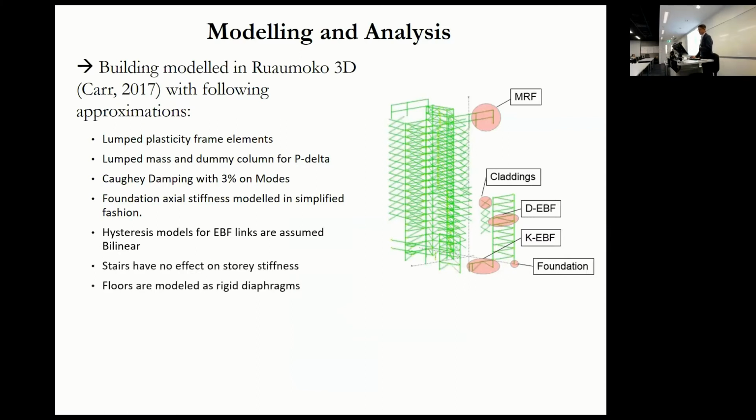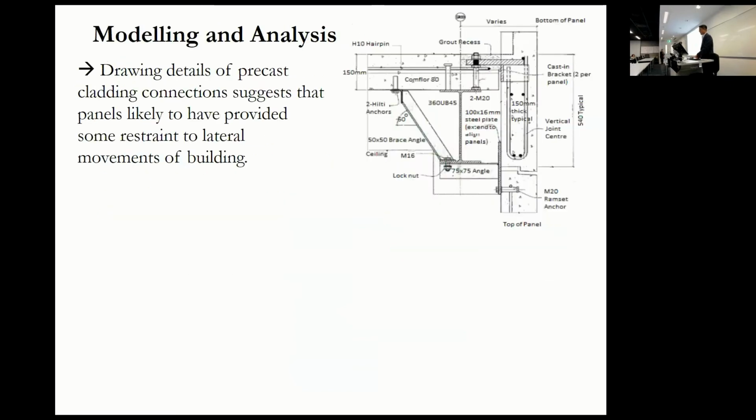Some other important assumptions perhaps is that the stairs have no effect on storey stiffness, and the floors are modelled as rigid diaphragms, and precast panels were modelled. So why did we model our precast panels?